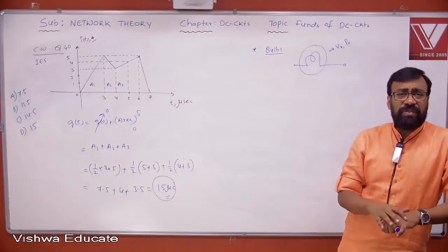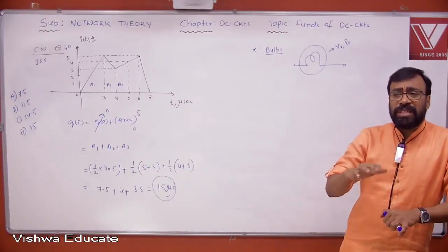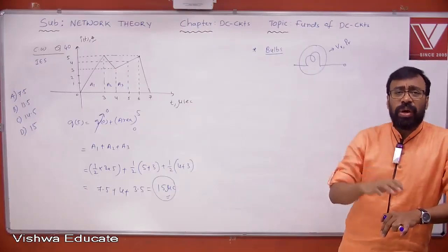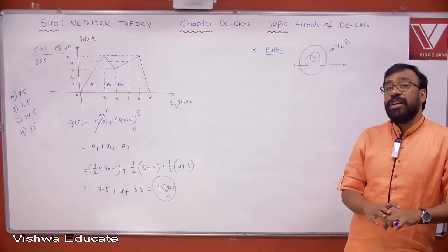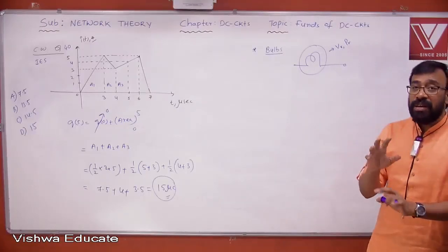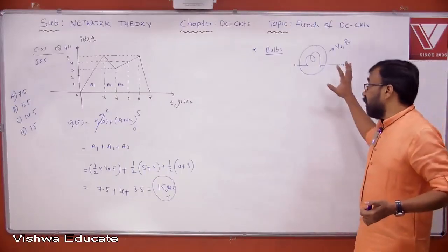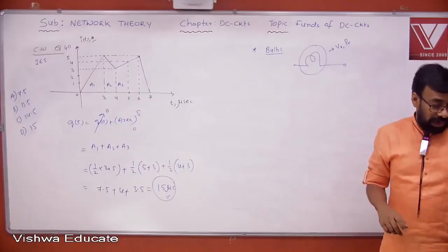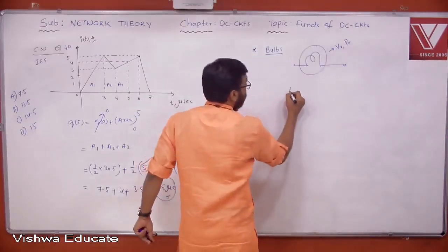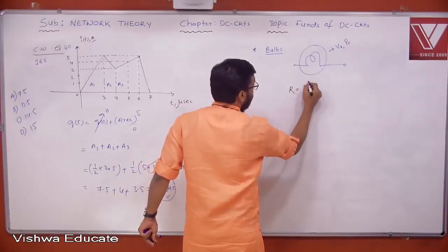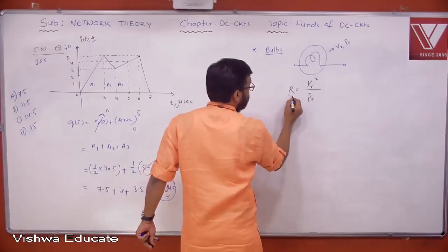Of course, the lighting effect will be a little lighter because the illuminance of that particular light will be lower, no doubt, but definitely it will glow. Whereas the LED and the tube won't glow properly. They simply flicker, and that won't solve your purpose. That is why people still use tungsten filament bulbs in remote villages. But when the bulb is given, generally the voltage rating and power rating are mentioned, and once you know the power and voltage, you can find the resistance of the bulb.